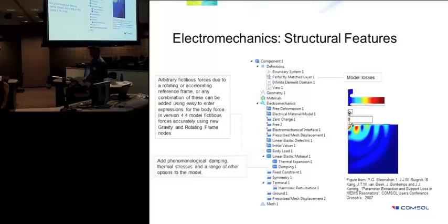Infinite element is another feature that is available when you do stationary models. Similarly, when you have an object that is infinite in size, but you do not want to model the infinity, you truncate the object and then you use infinite elements. But that's only for stationary models. Perfectly matched layer is for frequency response type of calculations.